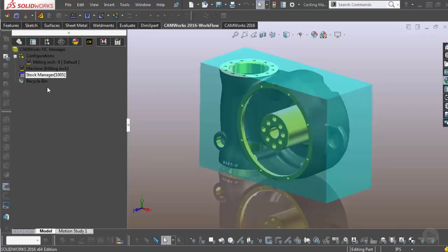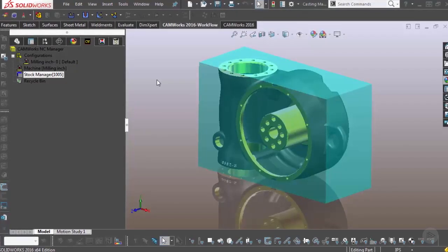Now, when you select that, it'll take into account all the information that you've put in over here in the Feature Manager and all the information you just put in the options, and then it will go ahead and try to find every feature, look at the part, do the milling setup, try to put in different setups if the part needs to be rotated, and work within the bounding box of everything that's been set. So if you set up everything correctly up front, you'll have a really good chance to have your part 80 to 95% done, depending upon how your technology database is set up.